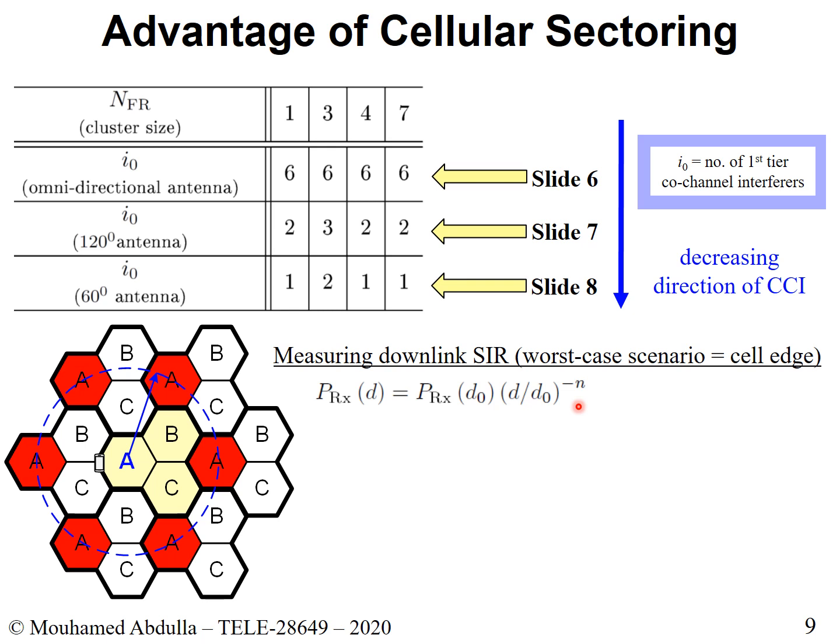However, I should admit to you that perhaps selecting something between 3 to 5 is better, especially if we are talking of deployment and measurement in an urban city, and that this received signal is highly impacted by shadowing, so different objects in the channel. So if that's the case, which is generally a good consideration, if you do your measurements in a built-up city, you could consider a value for the path loss exponent anywhere between 3 to 5.